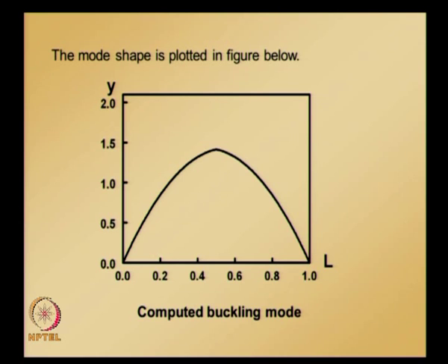So, now we have seen one application of this general one dimensional boundary value problem, which is the column buckling problem, and you have noticed that the evaluation of these integrals when we are solving this problem becomes simpler, because j happens to be a constant. If j is not a constant, then the integrand becomes complicated and we need to evaluate these integrals using some numerical techniques.